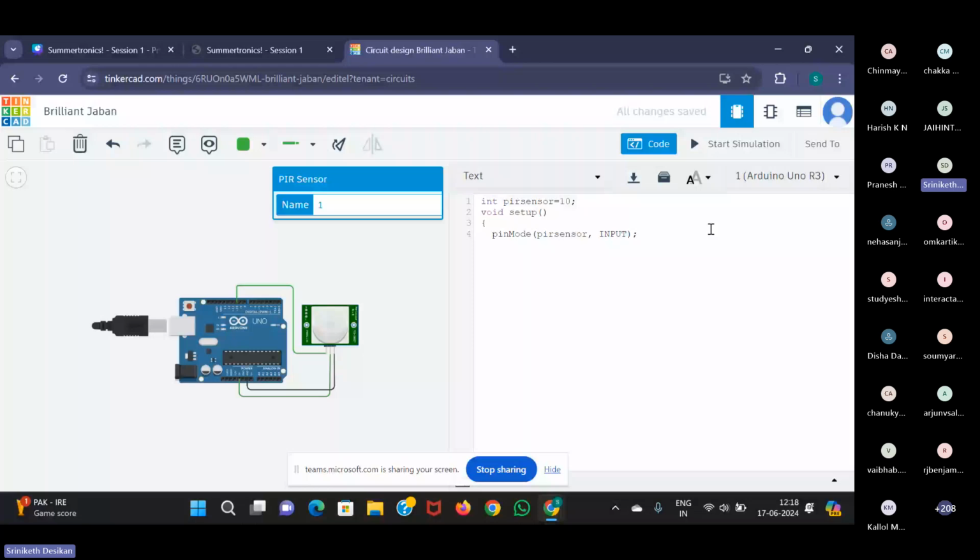To initiate the serial monitor, I have to give a Serial.begin here as well, with a baud rate of 9600. Now, I saw some questions earlier regarding why this number is 9600. It's just a standard number, and we really don't need any higher numbers beyond that.